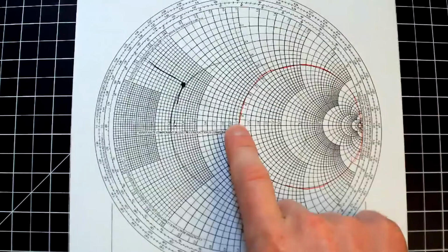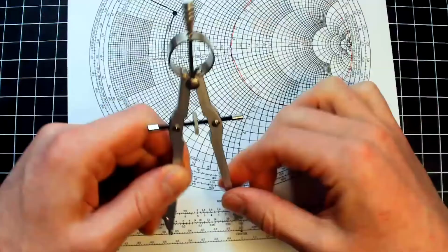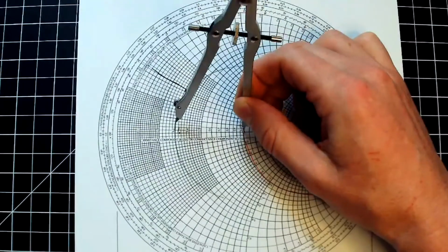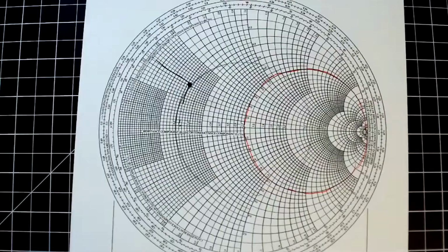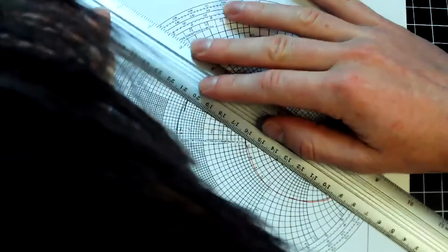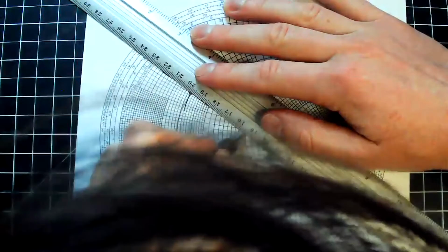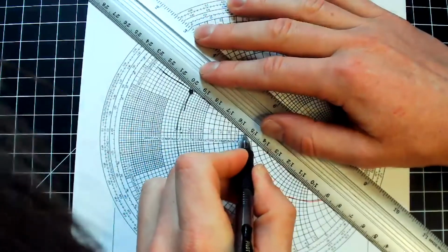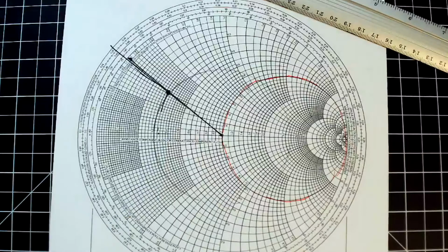One is just magnitude and phase of the reflection coefficient. So you saw I had the magnitude. You can read off right down here. There's the actual magnitude on this little thing here. And then the phase was 140 degrees. So it starts here at 0. Yep, there's 140 degrees. So if I go to 140-ish, like that. So this is actually a great exercise, by the way. There's 140, it was like 142, I think. So you just draw that line. And so there's two completely separate ways to get the same dot.